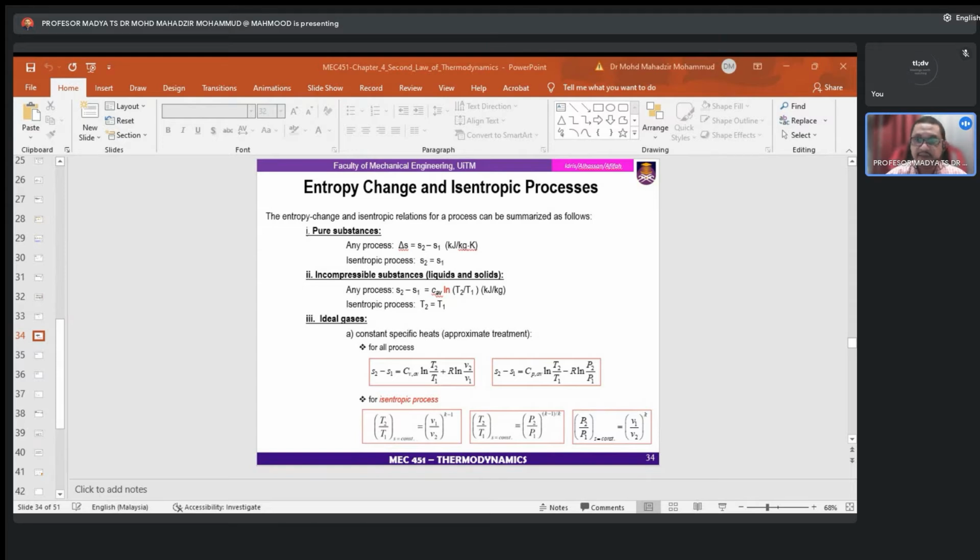Therefore, using a suitable reference state, the entropies of substances are evaluated from measurable properties data following rather involved computations, and the results are tabulated in the same manner as the other properties such as specific volume, internal energy, and also enthalpy.